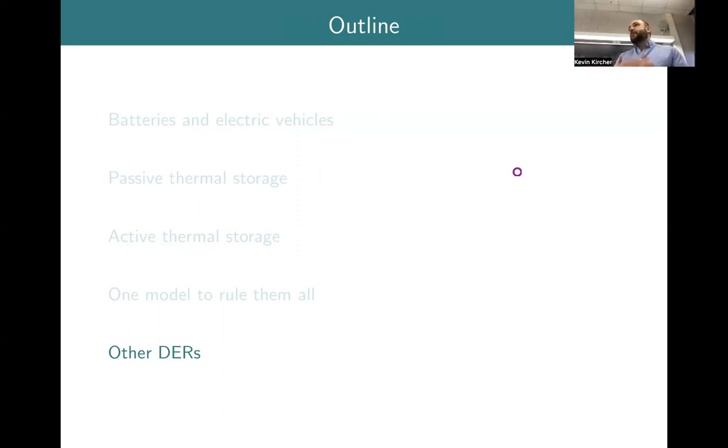So the idea there is that you have multiple levels of modeling fidelity. You might have a simple model, which they call a control-oriented or design-oriented model, which might be one of these low-order linear models. But then you have some deeper, richer model that has a lot of the nonlinear effects and a higher state dimension. Maybe it's a PDE model rather than an ODE model.